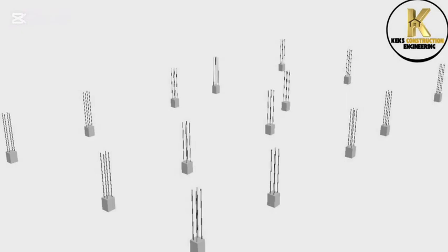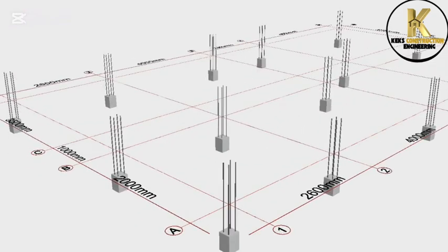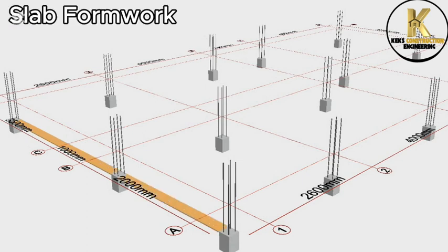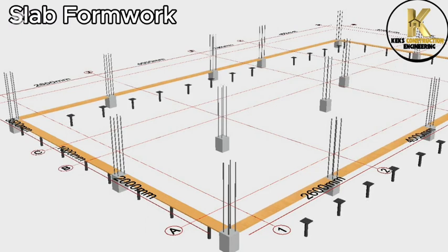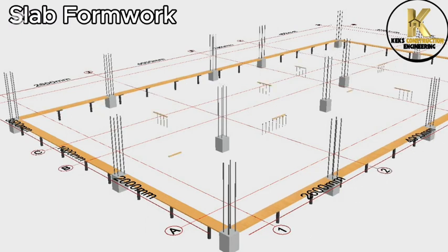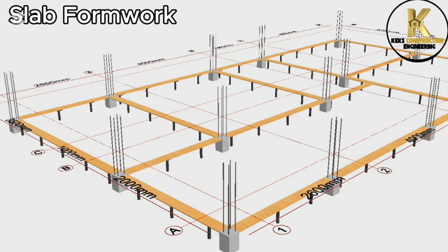Note, for better understanding, I cut off the down part of the building so we can focus and continue the slab reinforcement work from the top of these columns. I re-established the floor grid lines so we can construct and align slab formwork accordingly. Therefore, take note of the grid lines and dimension in the displayed detailed drawing so you can understand better.